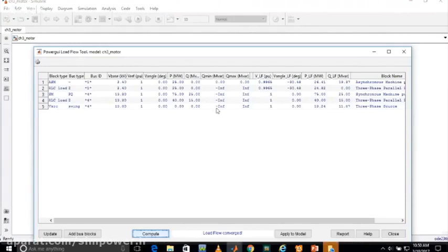And how much power is it delivering? Because P and Q is not defined for the swing bus, right? So this load flow is actually calculating the amount of power that is delivered by the swing bus, the SM, and how much power it is giving to the loads. As you can see, the amount of power the ASM is getting is 26 megawatt and 19.37 MVAR. Similarly, our RLC load of 40 megawatt and 15 MVAR is required, and our synchronous machine is providing 75 megawatt active power and 25 MVAR reactive power. It's showing it there.